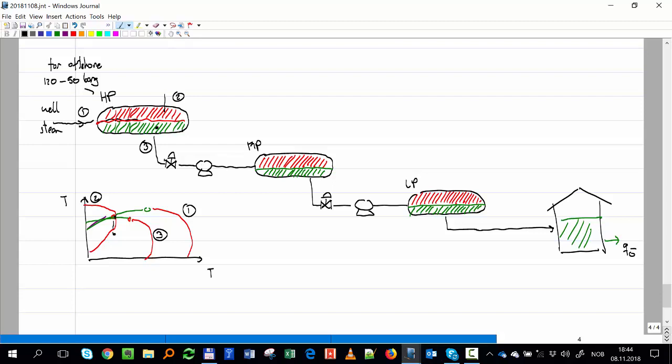And then I have another pump here. So that's very critical. Offshore it is very simple to make. Onshore, we have to dig a cellar and put the pump down, or we have to make sure that we don't get any vaporization. Remember that it's not only at the suction of the pump, you have another pressure drop when it gets to the rotor.